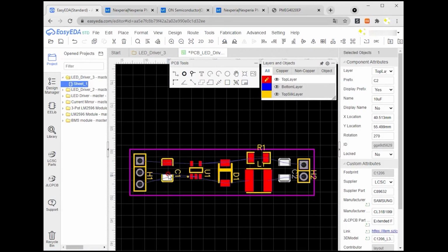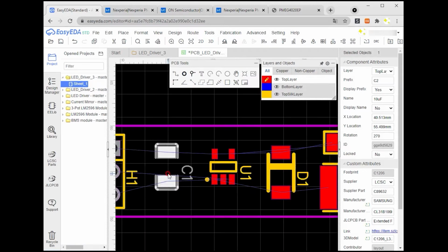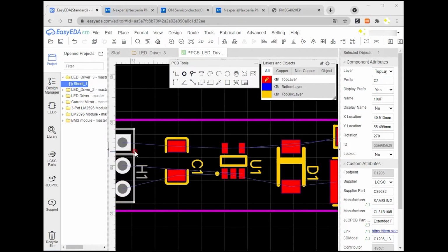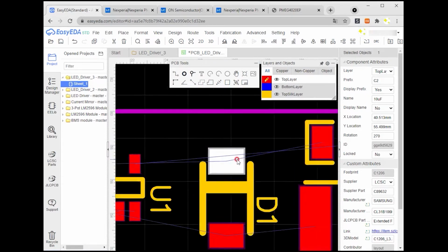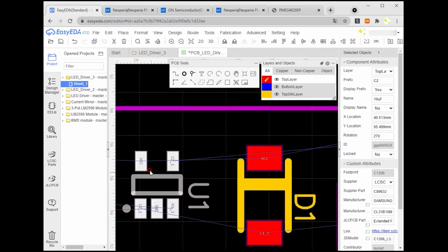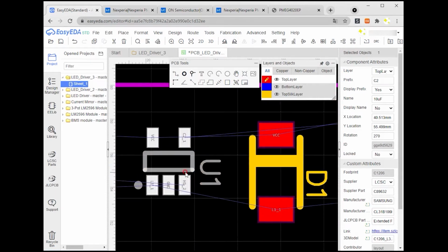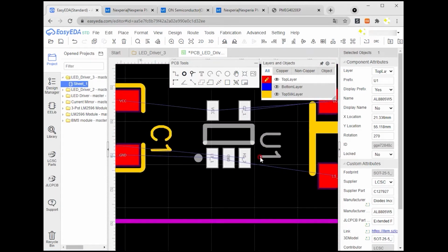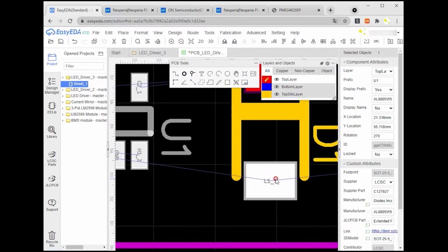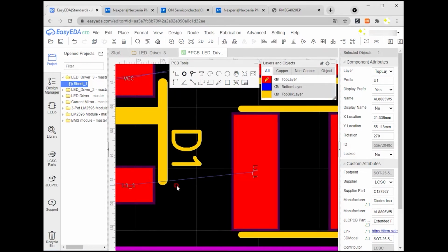Now, we need to make connections between the components. In general, the connection of VCC and GND should be done by a plane, for a low impedance path. VCC is connected with C1, U1, D1, and R1 through pin 1 of H1. So it would be nice to make a plane connecting these pins. Also, the path connecting pin 1 of U1, D1, and L1 is also the part where the main power passes, so I will connect it as a plane.